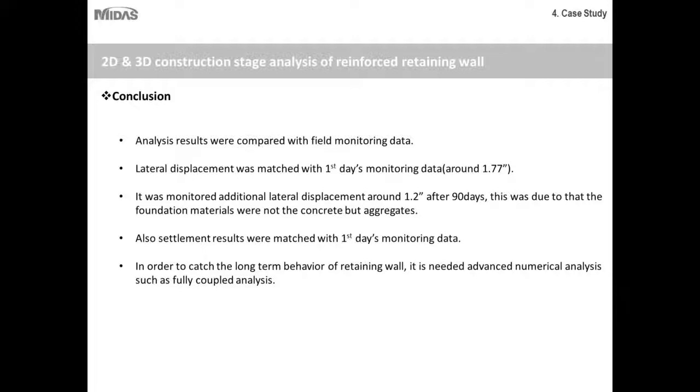I'm not sure what drainage facilities were available on that site, so I cannot comment to what extent coupled analysis would be needed or helpful, but definitely we can say that the strata was clay, and no matter how good the drainage condition is, you would definitely have some built up pore water pressure that will take some time to dissipate.